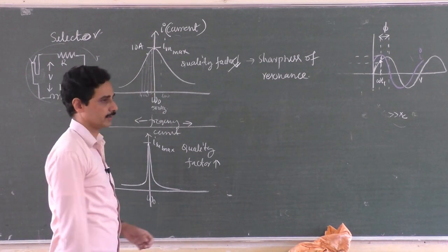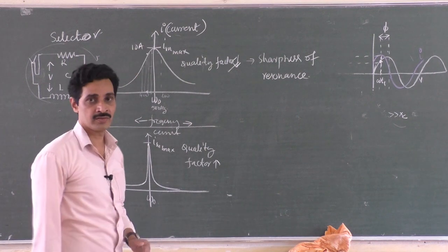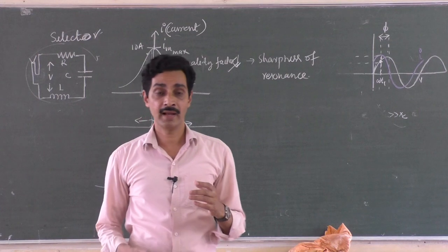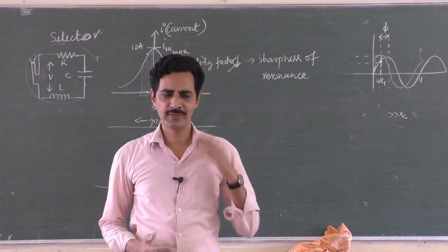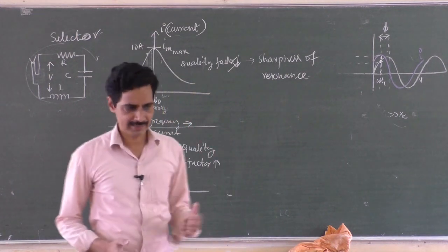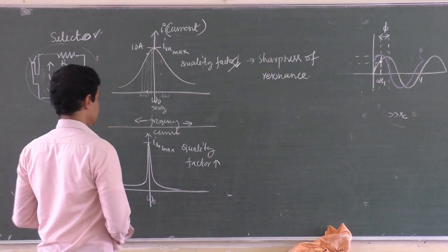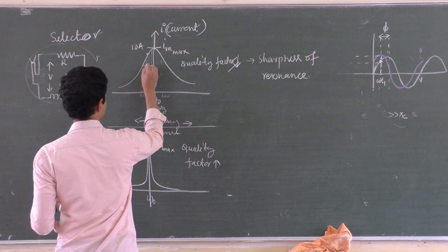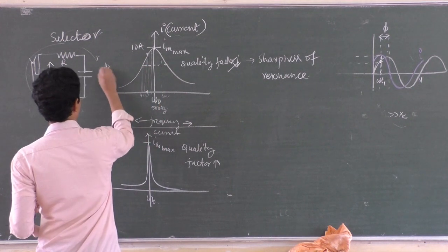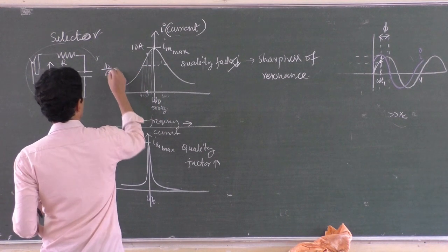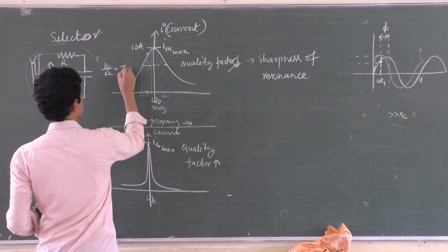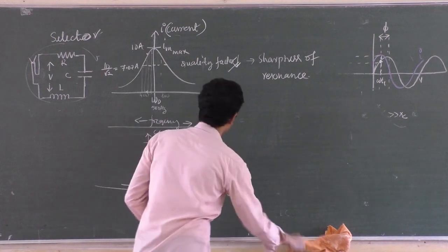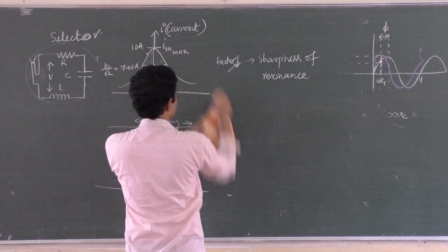Now we will come to this circuit. Current is maximum at resonance, right? Now you select some currents which are neither maximum nor minimum. Sir, which amount of current will I select? Let us select a current which is about 1 by root 2 of this current. What is 1 by root 2 of 10, sir? 10 by root 2, that is, 1 by root 2 is 0.707, say 7.07 ampere. 7.07 ampere is not a bad current, right? It is a fairly good current.